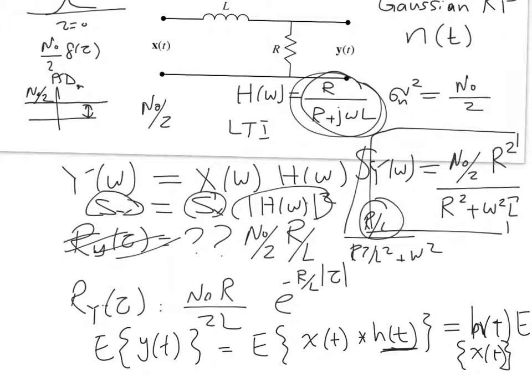So in this case, you have to get the variance through the idea of a Gaussian random process going through a linear system. Then the output sigma is going to be scaled by the factor of the system, which is this magnitude. So actually the sigma is going to be a function of omega.